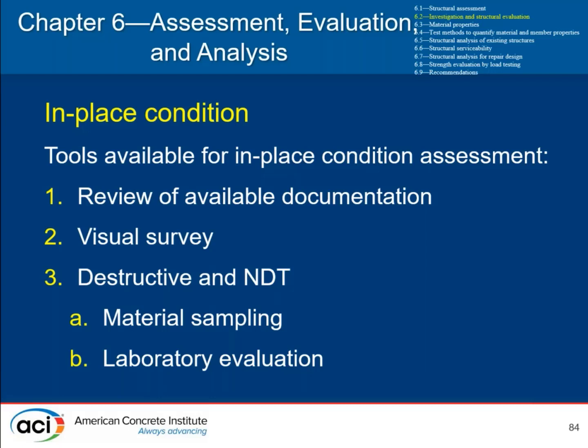You're almost certainly going to be visiting the structure to carry out a visual survey. You're going to be doing destructive and non-destructive testing to sample materials, and you may be carrying out other laboratory evaluations to assess deterioration or corrosion-related quantities or features that may be present in the structure that you're assessing.